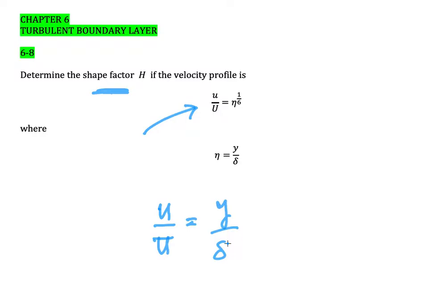But if we see the notes from Blasius, how they do the Blasius exact solution, because there is a lot of components, to simplify the equation, they will compile all the unknown parameters into an eta here.